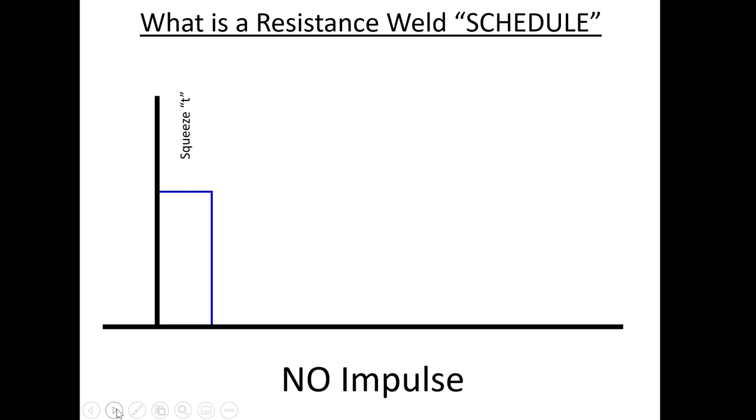And the oil is in there to take the place of air so it can more quickly react to initiation. When I'm asking for force, I get it very quickly because I don't have all the compressible gas, air that is, inside the cylinder. So it reacts very quickly to the application of air pressure. And this speed helps with our timing cycle. Then often we have an upslope. I usually put an upslope in everything, so it makes it very easy to make initiations.